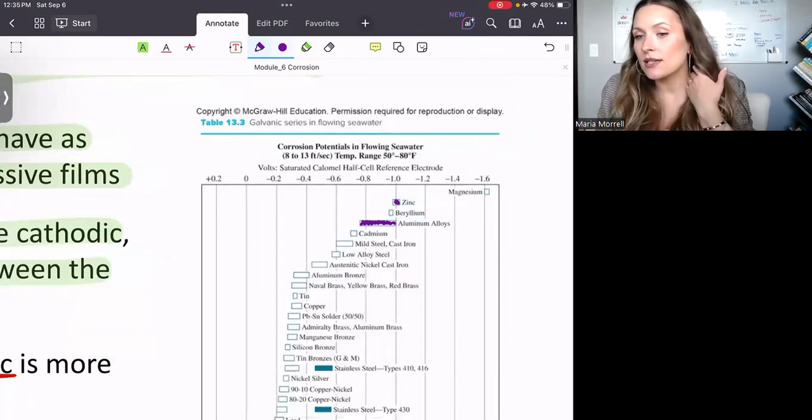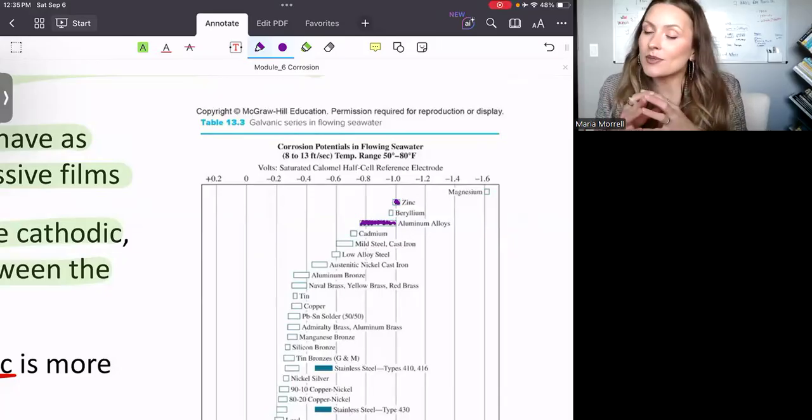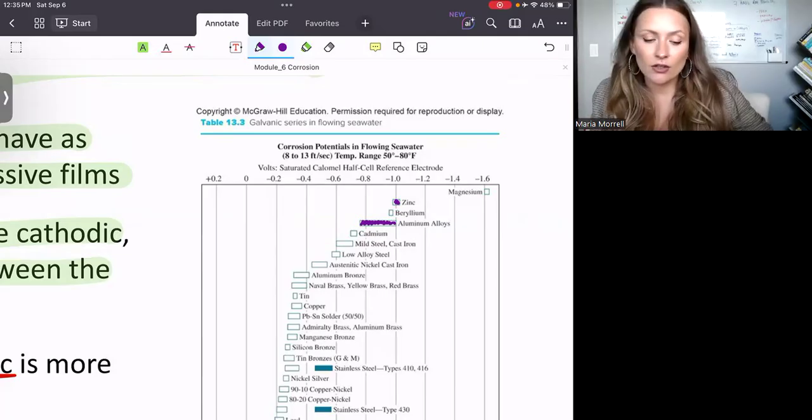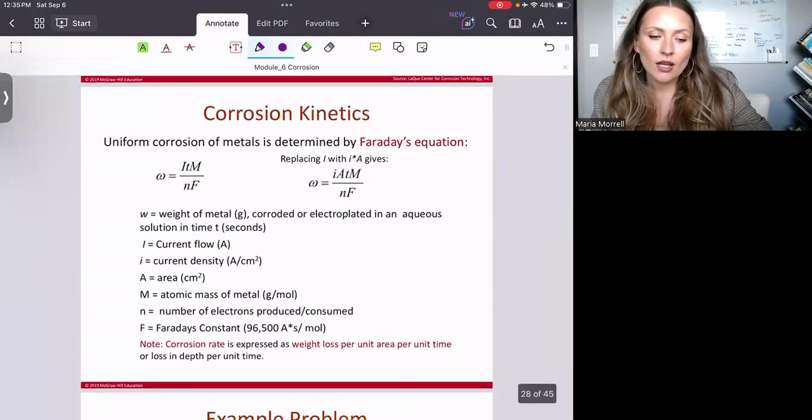I will be giving you some examples where you have a bunch of pipes connected, or certain pieces that are connected with each other, where you have to identify and spot the examples where some kind of insulation layer should be inserted to prevent galvanic corrosion.